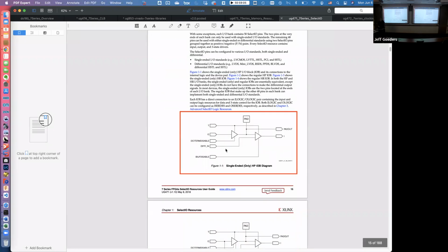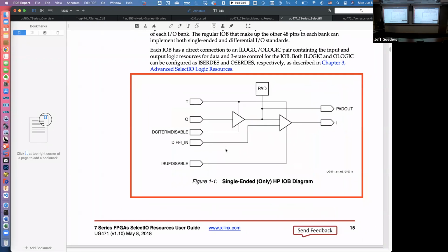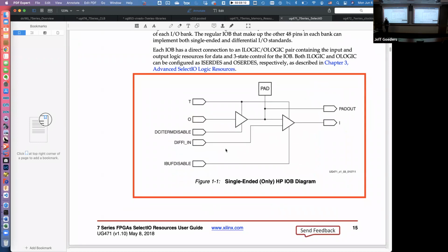Here we go. Here's an example of an I/O cell. So let's look at it. This is the wire that goes to the chip package, the outside world right here, okay? The pad. Now notice, if you just want to come in, you can come from the pad and you can go into this buffer right here, and that will then come into the circuit.